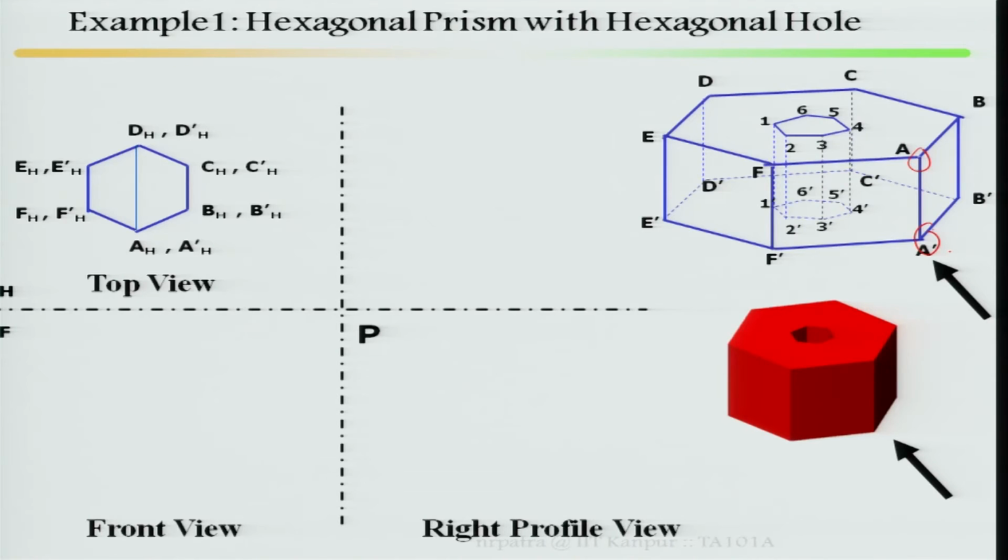Then come to your mark, inside. Draw a circle, then draw your inside hexagon. Once you draw the circle, you can do it very easily for the inside hexagon. Then mark it 1, 1 prime, 2, 2 prime, 3, 3 prime, 4, 4 prime. If you look here, this point is your 1 and 1 prime. Similarly, this is your 2, 2 prime, this is your 3, 4, 5. I just put it arbitrarily, 1, 3 and 5.